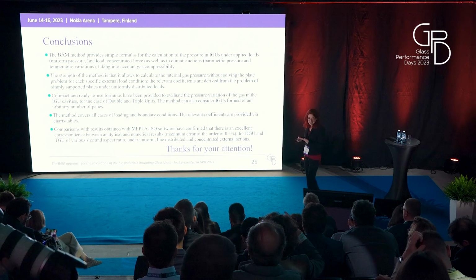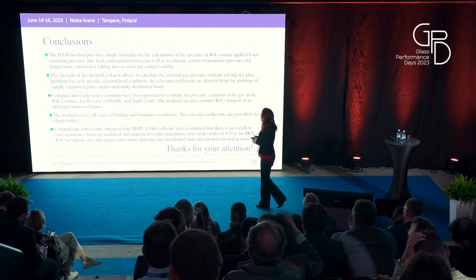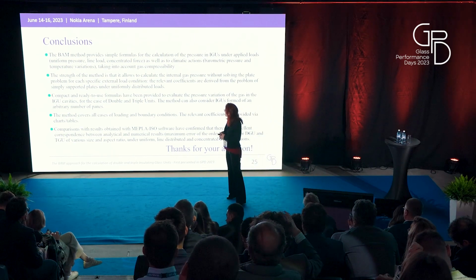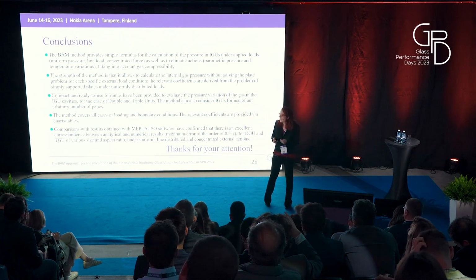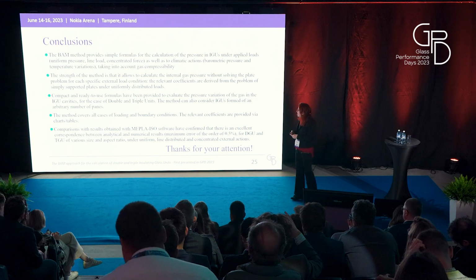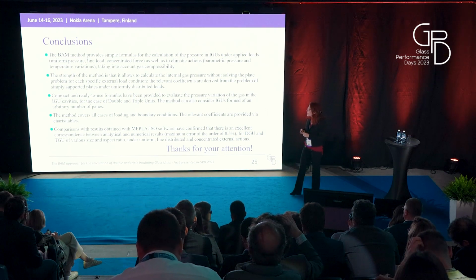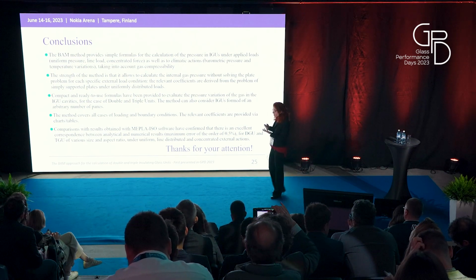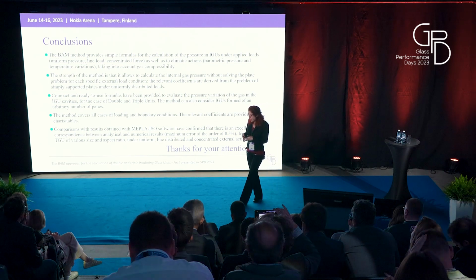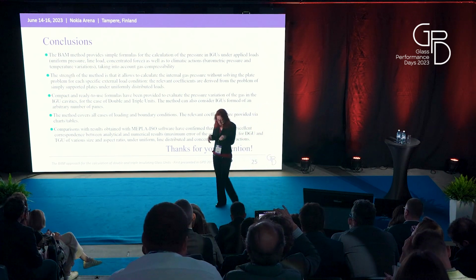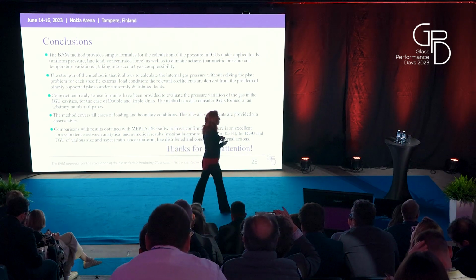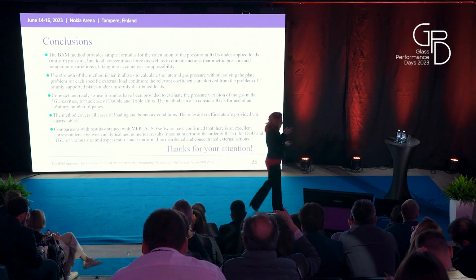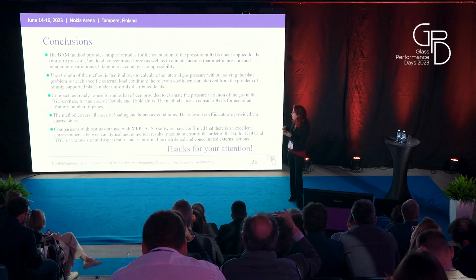Here I have not presented the results for reasons of time, but accurate comparisons are recorded in different papers. And the strength of this method is that it does not require solving the problem of the plate under the concentrated or line concentrated load, but it only requires the knowledge of the coefficients phi A, phi P, and phi L.